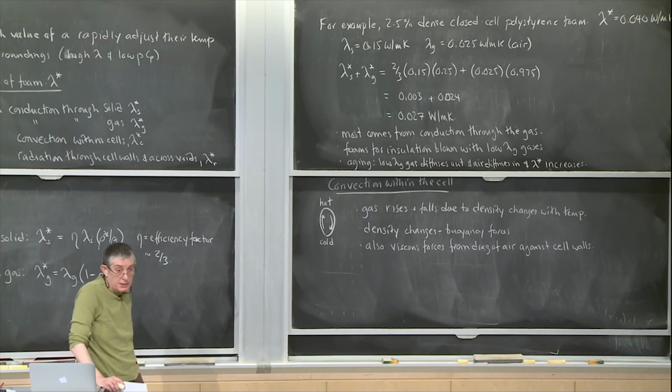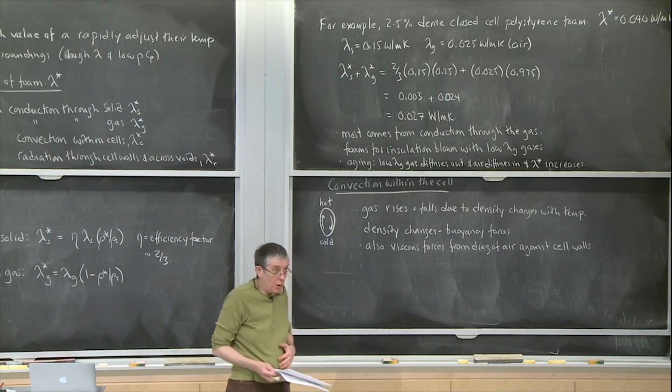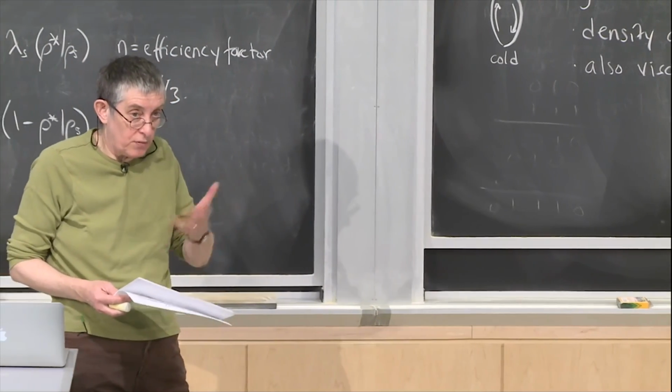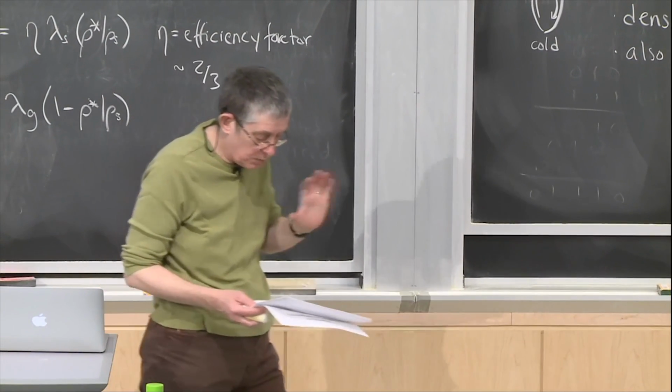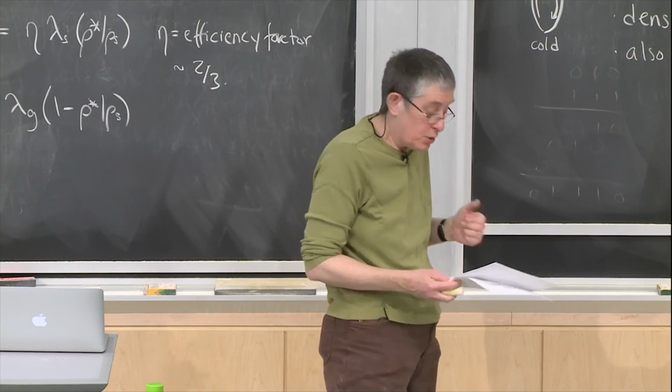And in fluid mechanics, they often use dimensionless numbers. And there's a dimensionless number called the Rayleigh number. And the Rayleigh number, you can think of it, it's not quite the balance of the buoyancy force against the viscous forces, but it involves those forces. And convection is important if this Rayleigh number is over 1,000.